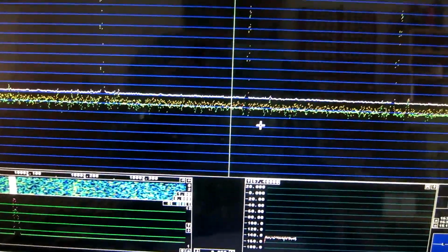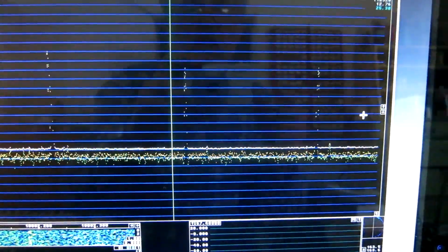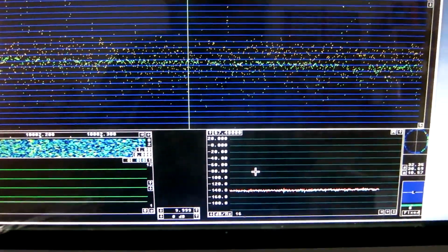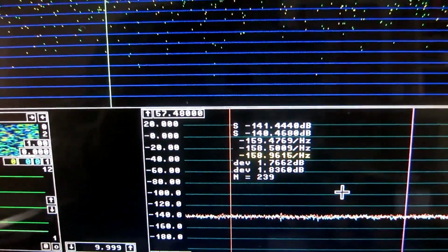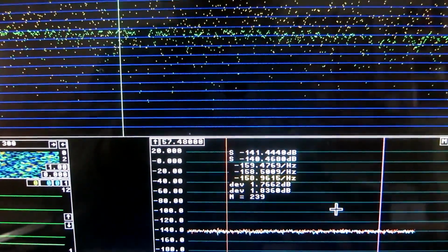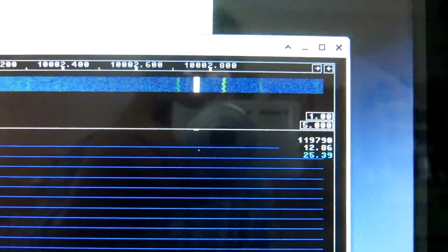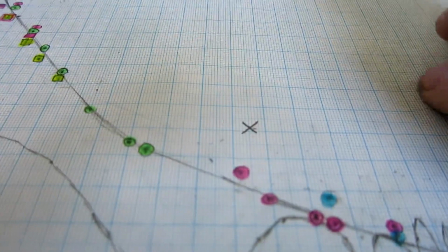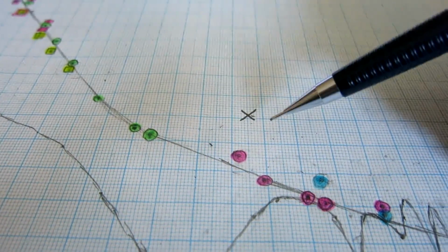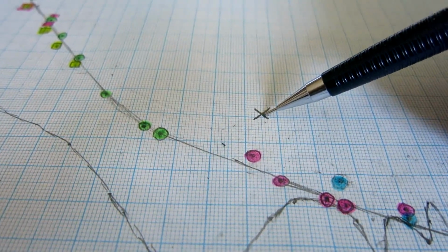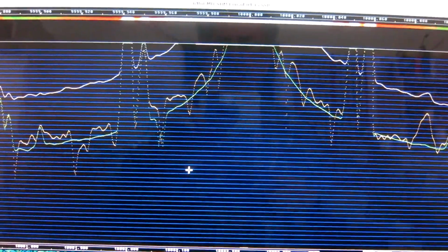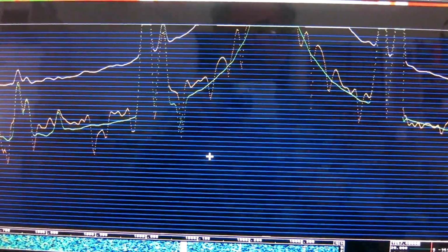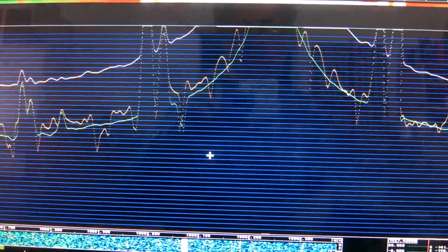To see better, I will expand the vertical scale. I see minus 159 dBc per hertz, and 12.8 dB advantage. That's minus 171.7, and it comes here. I have saved the screen, and also this one, which is expanded in the X direction.